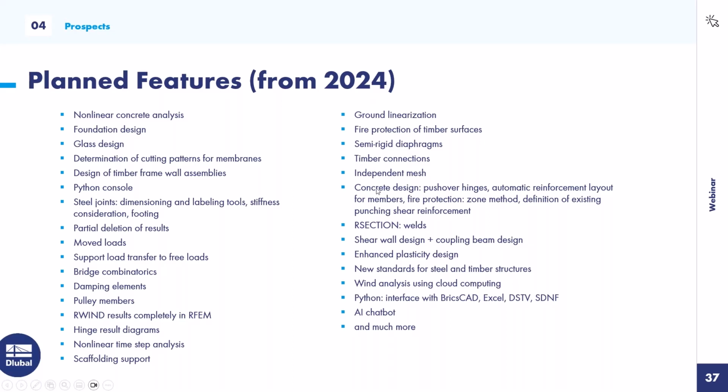Then now I am at concrete design. It can consider pushover hinges and the pushover properties depending on reinforcement. Then the automatic reinforcement layout for members. For the fire protection, we will implement the zone method, and then the definition of existing punching shear reinforcement.